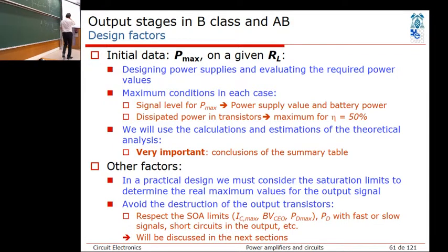Also the peak powers. And of course the voltage level. And then this amplifier itself, okay, you are dissipating quite a lot of power there. So for 100 watts, in the worst case, you are running 20 watts on each transistor if it's a sinusoid signal. Okay, still, if it's sinusoid.